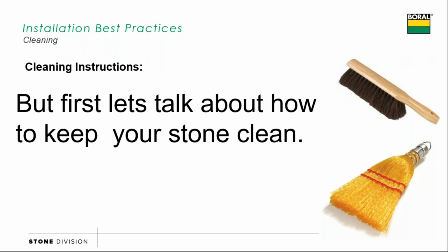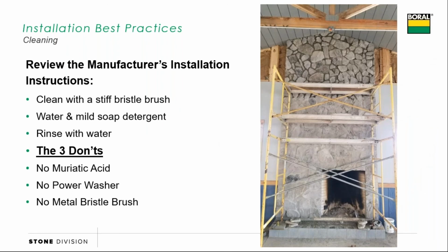So again, my job as a tender was throughout the day, brush it down, lunchtime, a really good job of it. And then at the end of the day, as they hop in their trucks and I'm cleaning up, my job at the end of the day was to go through and brush it down one more time. We never had any callbacks for fingerprints and mortar smears that way. So when it does come to cleaning some dirt and dust, warm water, mild detergent, soft bristle broom will take care of most things. Please, no acids, no power washers, no metal brushes.